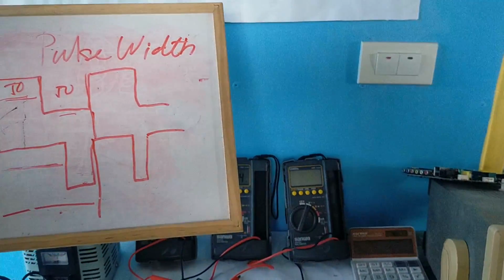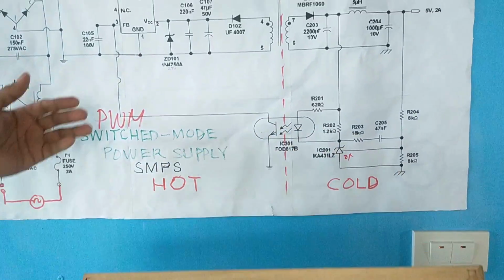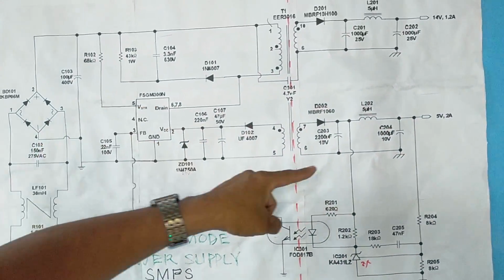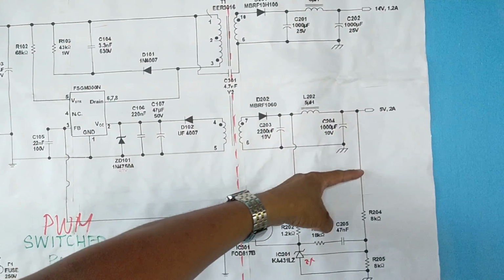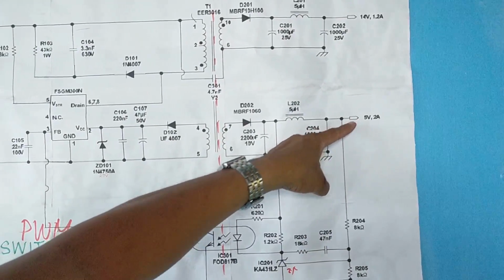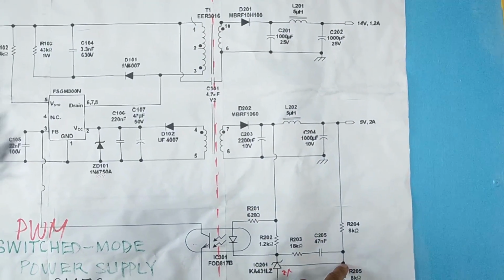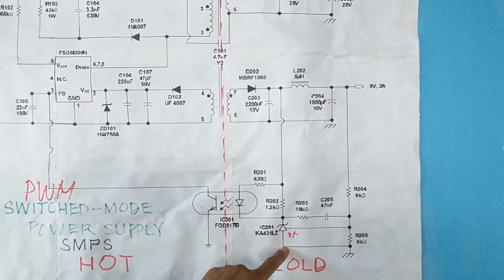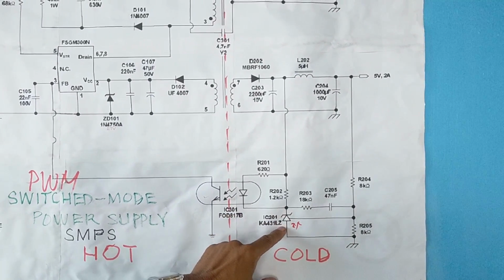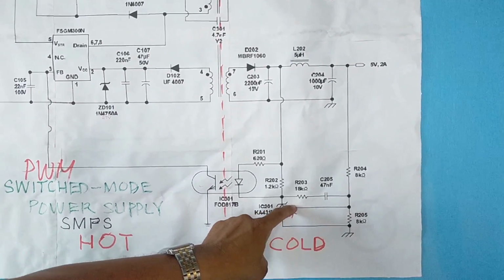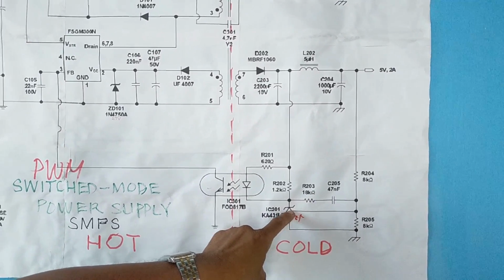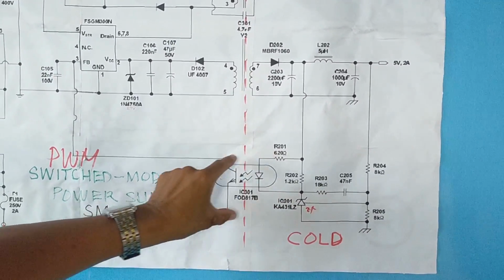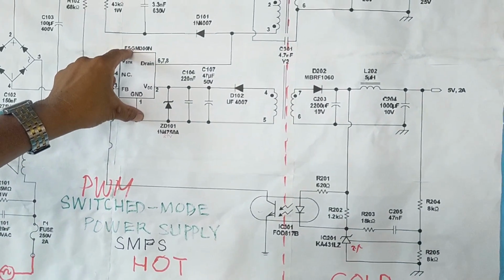But if there's a need of increasing the operation of the transistor here because there is a decrease of voltage at the output from 5 to 4, so 2 volts here being compared to the reference of this precision shunt regulator, which is 2.5, there's a difference of negative 0.5. So that will be fed back to the control IC.